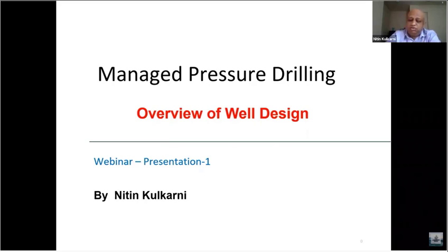Now, today's webinar is an overview of well design. We focus on the well design aspect, assuming that we are going to drill a particular section of the well using MPD. We will review what changes we need to make in the well design. This is usually important in the beginning phase, but as you develop this technology for your field and your drilling operations, these things become part of the routine procedure.